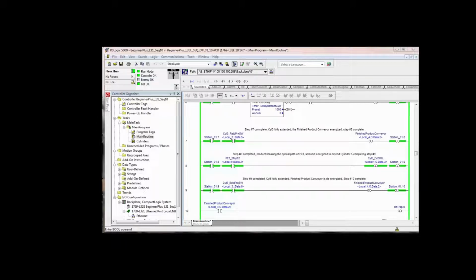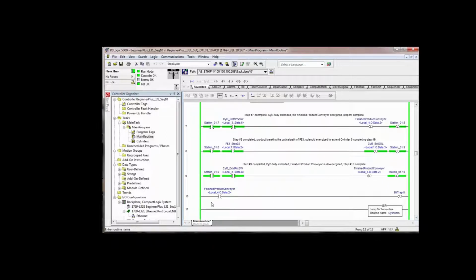Now, again, this doesn't hurt anything, but it's something to keep in mind so you don't get confused. Notice that I added in a rung here. So I'm looking at that actual bit. If this bit was actually still on when you get to rung 10, then it would latch this bit and it would stay latched. Now, you just saw it go on again.